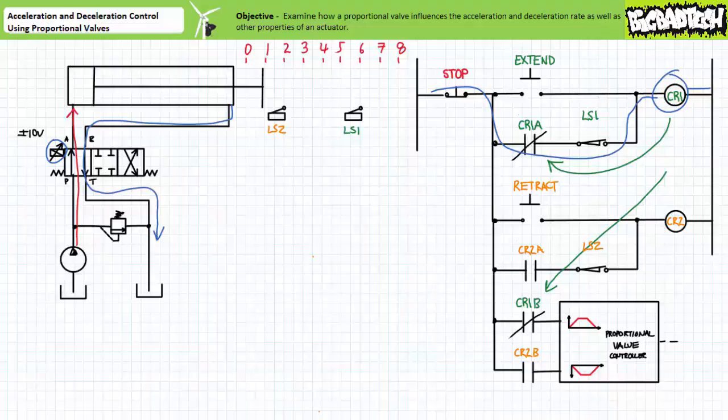At a certain minimum voltage, the dead band is passed and the proportional valve cracks slightly open, allowing a minimum amount of flow. Flow rate goes from 0 to the tiniest trickle. The cylinder and applied load slowly creep forward. This being said, the movement of the cylinder and applied load steadily increase as applied voltage is steadily ramped up to positive 10 volts and the proportional valve is progressively opened more and more.